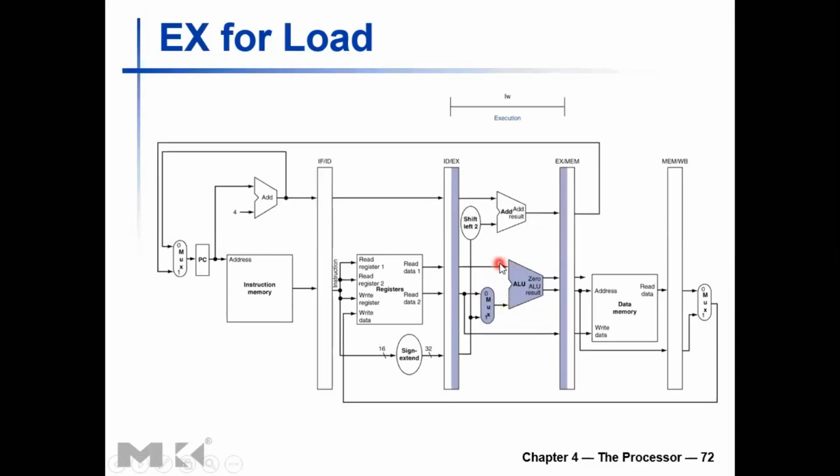A little bit before that, you will have the other operand to the ALU available. Then after the ALU's delay, whatever the delay that the ALU takes to do the addition, and some extra delays for whatever other multiplexers you have inside the ALU, you will have the updated result here, right?